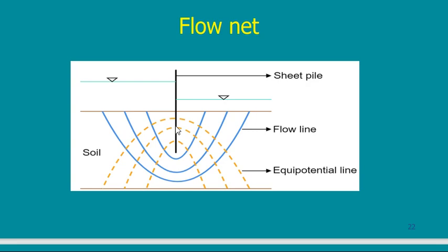I should draw flow lines so that I can sense that the amount of water passing within these channels are the same in every one. So suppose that you draw your first flow line here. In this case, you will have to draw your second one here. But suppose I draw the first one here.